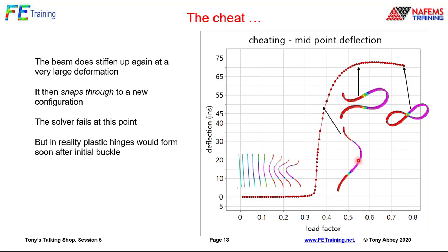Initial buckling, when a nonlinear buckling, may have plasticity present prior to buckling, developed during buckling, but probably most structures pretty soon after they start to buckle, they're going to have a plastic mode. Now whether we're interested in that or not is another matter. Probably by the time we get to this point in here, we're pretty happy that it started to buckle, and that's enough for us. This is really just a collapsing type of structure. There's no real stiffness that we're interested in here.